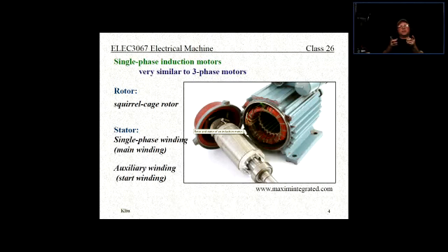But we just provide the change of those windings, the way the power is applied to the windings. It's solved a little bit different because we only have the DC, so we have to do something else, which means we're going to have a commutator, which is going to switch the direction of the polarity of the coils by the way the commutator works. And we only have DC.